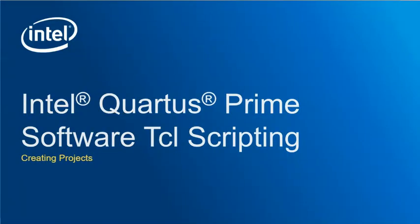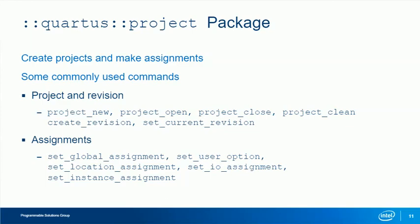Now I'll introduce the first sample application of the Intel Quartus Prime software Tcl API, which is creating projects. The Quartus Project Tcl package includes commands for creating and working with projects and revisions, and for creating and working with assignments and settings. The commands listed here are a subset of commands available in the project package.